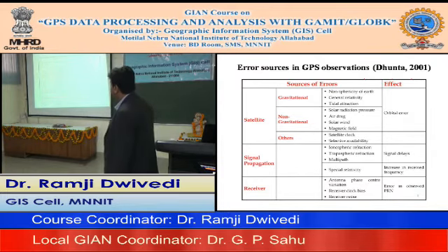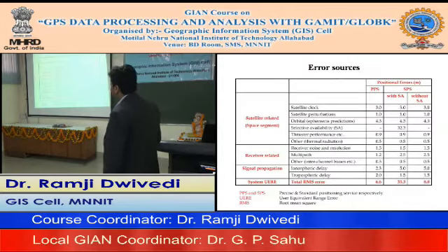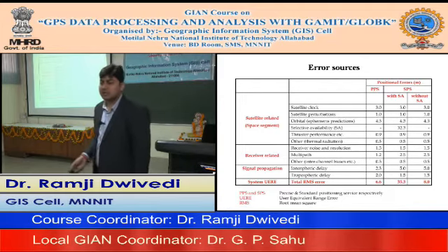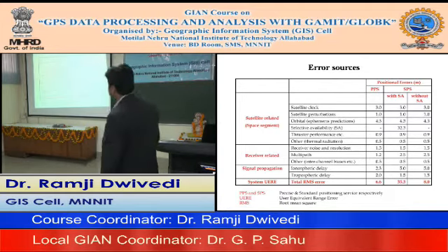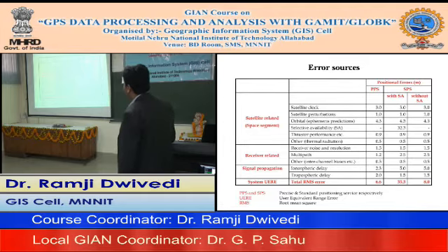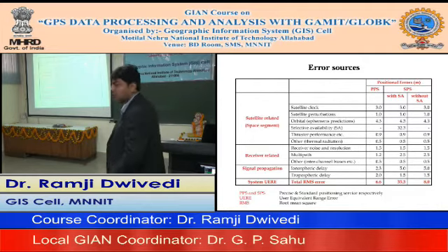There are two services which we couldn't cover just by saying this: the precise positioning service and the standard positioning service. When we are using the C/A code, we are actually working in the SPS, and when we are using the P code, we are actually working in the PPS. Because of these two services, the codes we are using are classified into two categories. For the satellite clock, there is the case without selective availability and with selective availability, which could be more, eventually, with selective availability.